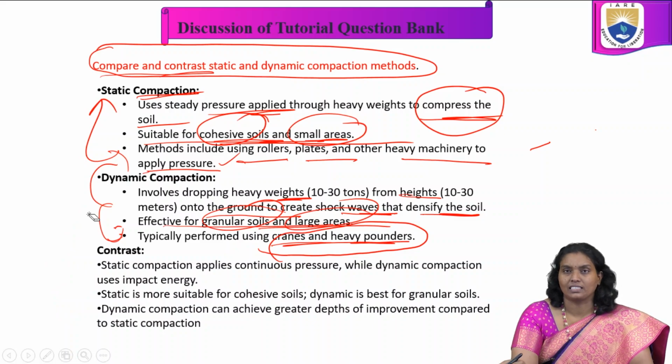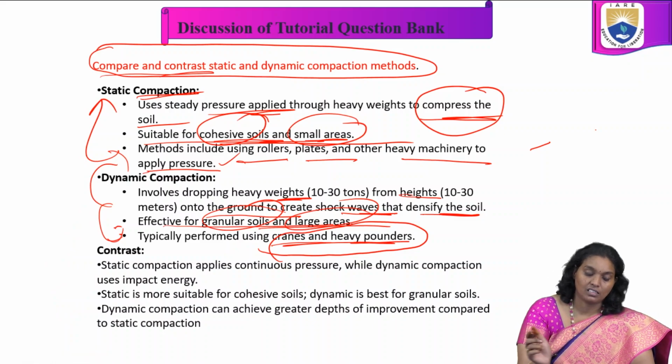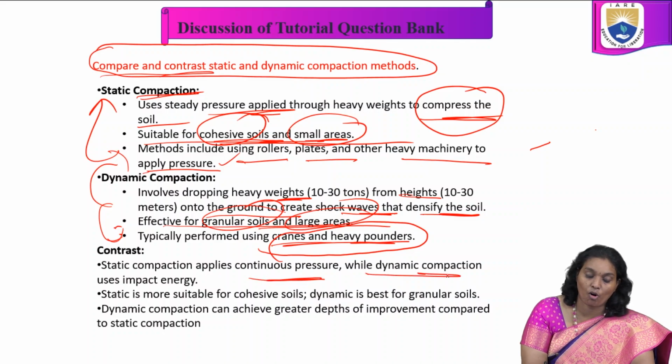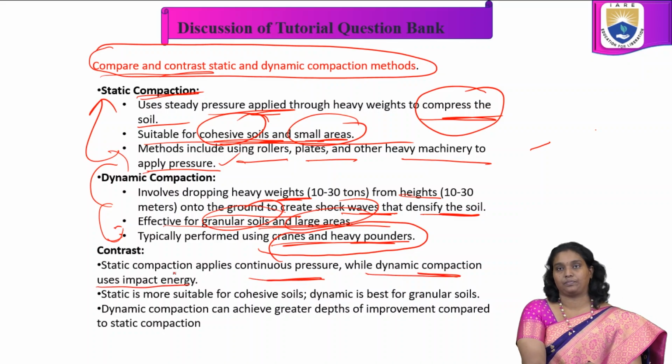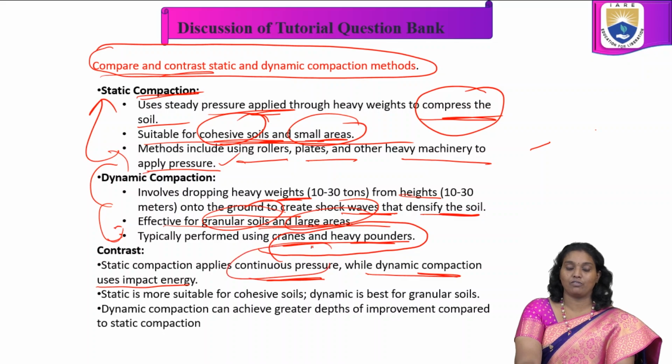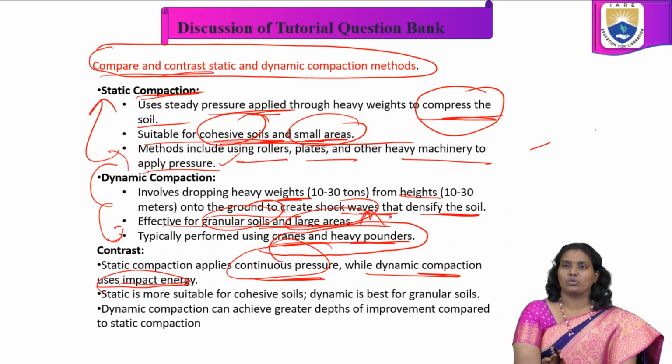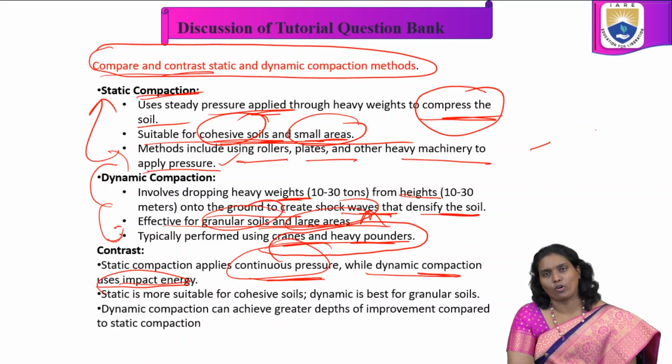Now the contrast. Static compaction applies continuous pressure, while dynamic compaction uses impact energy, the shock waves. So densify, shock waves, impact energy, continuous pressure: these are the terminology we must use in this kind of question, and using terminology is very, very important.